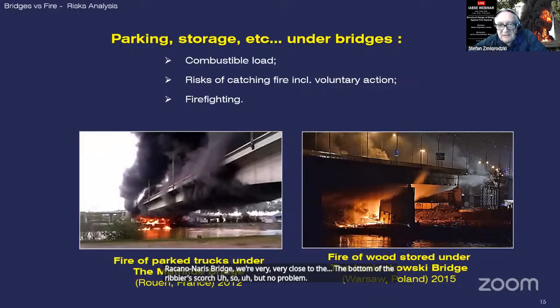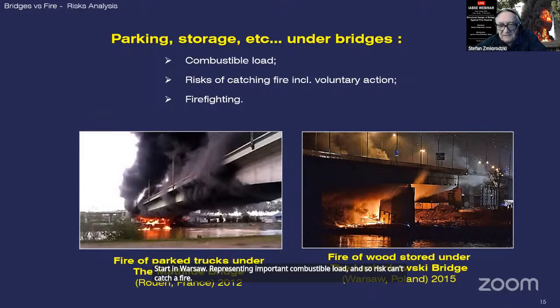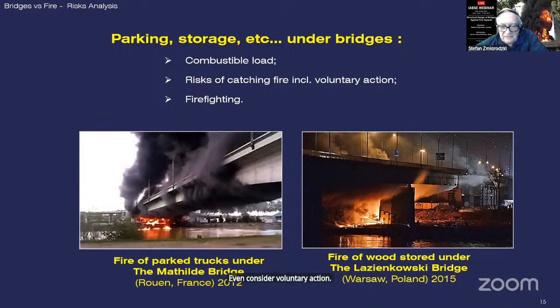Parking and storage under bridges. We had examples shown below from the Matilda Bridge in France and the main bridge in Warsaw, where the stored material was parked cars and trucks in France, or wooden decks stored in Warsaw, representing an important combustible load and so a risk of catching fire. Even voluntary action should be covered. Firefighting is another element we should keep in mind.